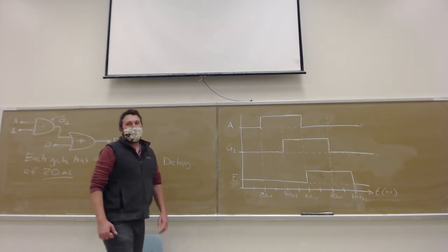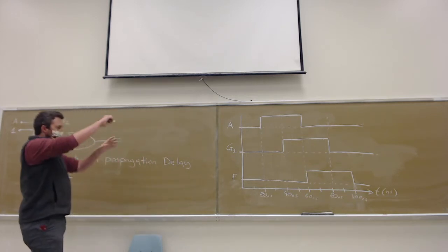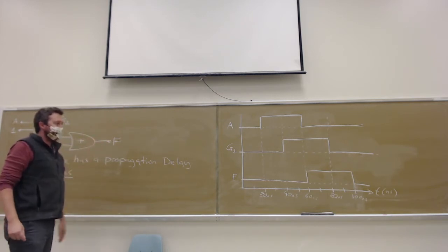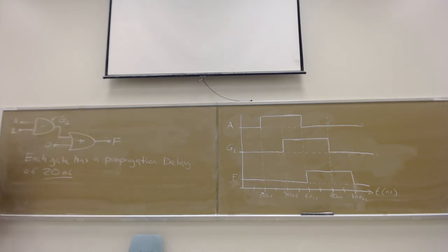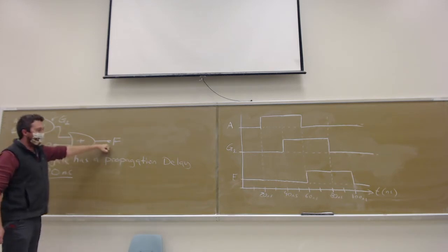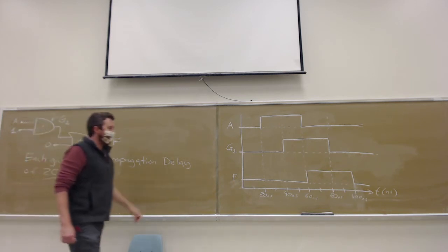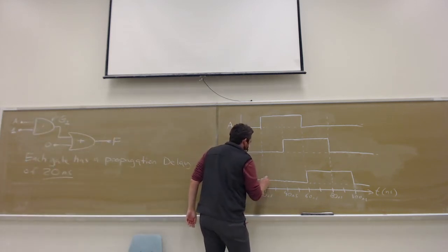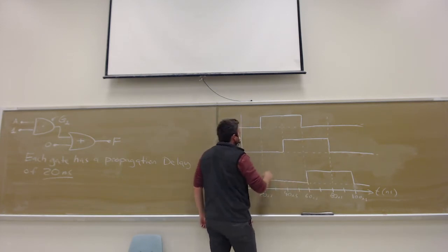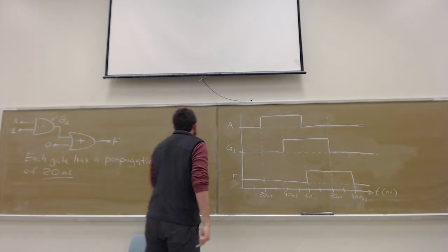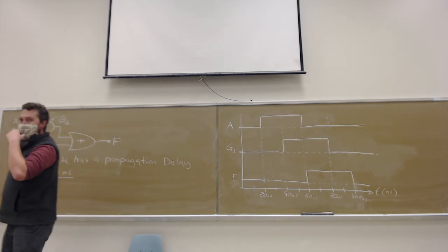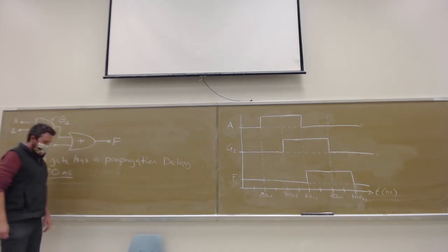So there are a couple of interesting observations we can make here. First, we can see how the logic structure settles out. But also we can see how long it took, when we changed A, for that output to appear on F. It took 40 nanoseconds. So there's a maximum circuit propagation delay of 40 nanoseconds from the time we hit go until we saw the result on our output. Those propagation delays stack up as we add more and more circuits to the system.